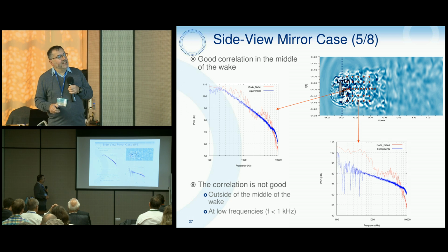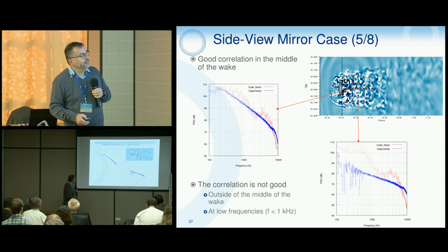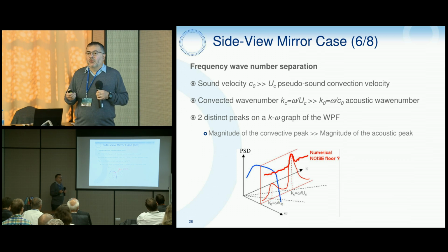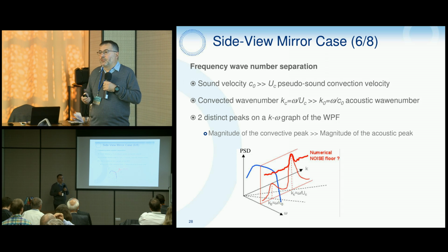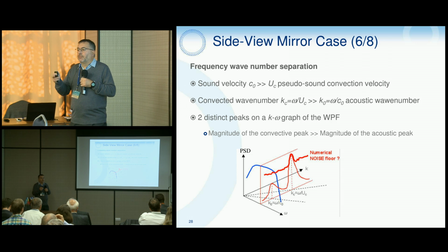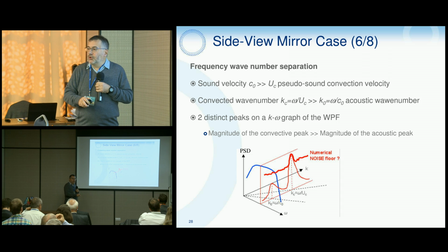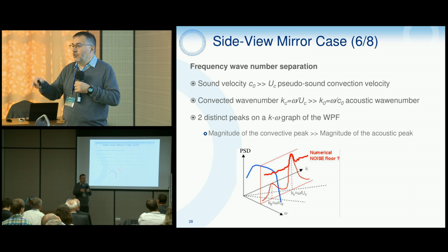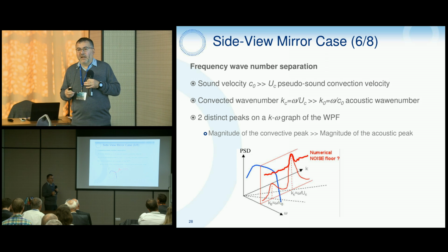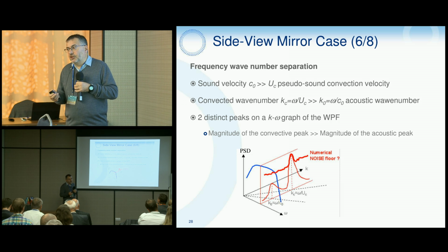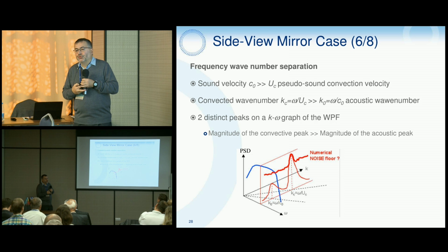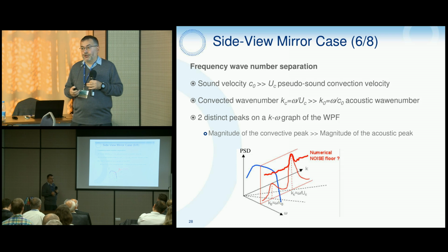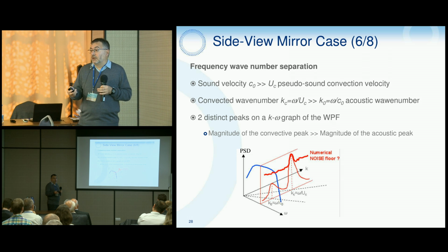Here again it was in the low frequency range. In fact, what was the main objective for PSA Peugeot Citroën? They wanted to be able to separate the contribution of the convective fluctuation and the acoustic fluctuation present on the side window to the noise radiated in the interior, because especially for the acoustic fluctuation, it was not easy to calculate. If you don't have really high fidelity simulation, it's not easy to calculate this contribution. And it's also not easy from an experimental point of view.